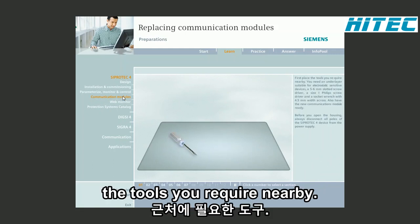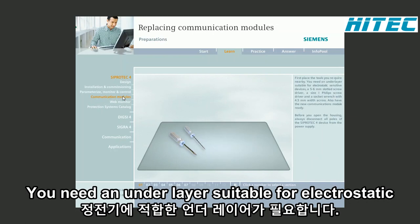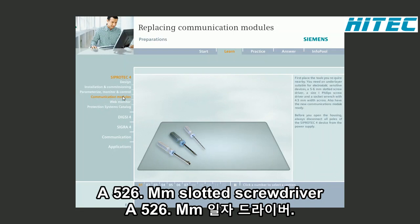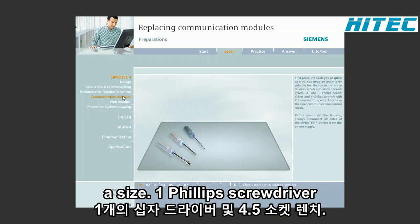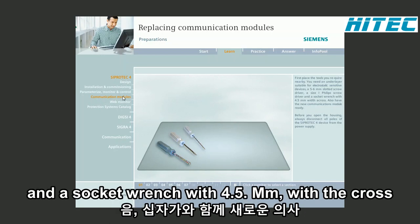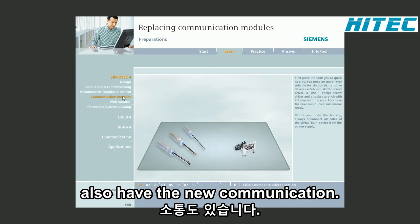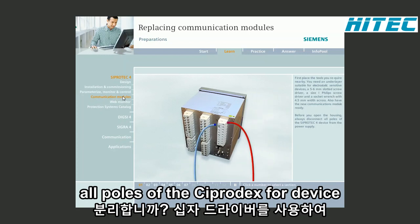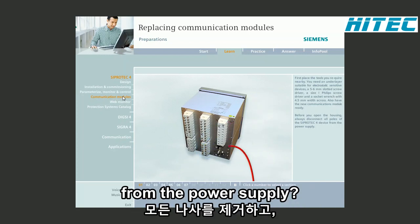First, place the tools you require nearby. You need an underlayer suitable for electrostatic sensitive devices, a 5 to 6 mm slotted screwdriver, a size 1 Phillips screwdriver, and a socket wrench with 4.5 mm width across. Also have the new communications module ready. Before you open the housing, always disconnect all poles of the SIPROTEC-4 device from the power supply.